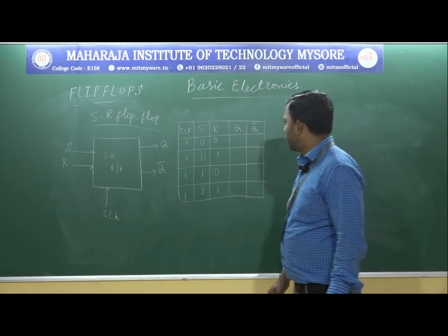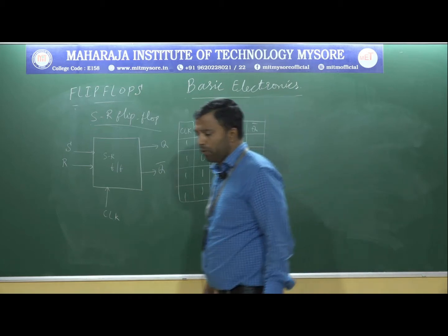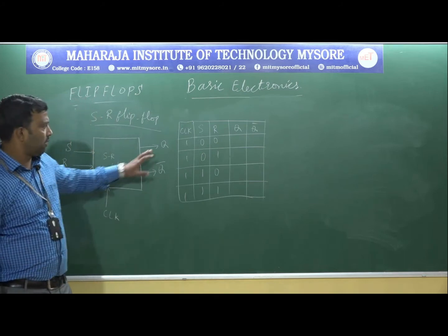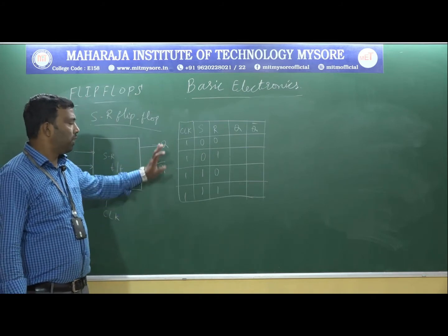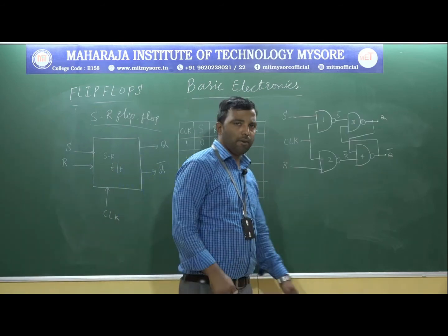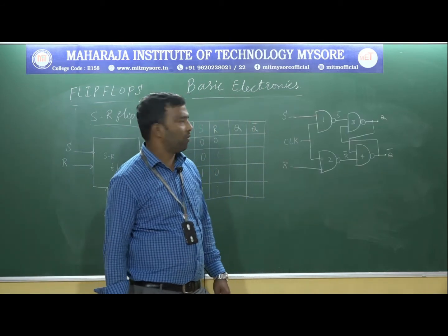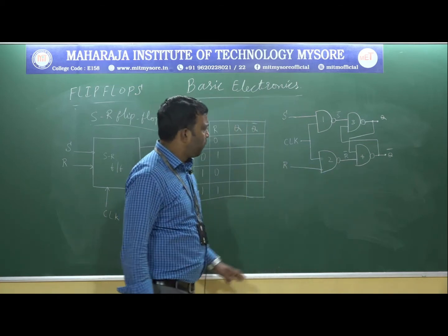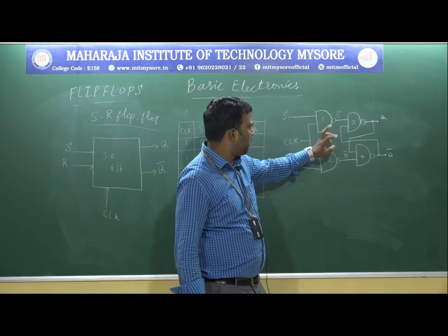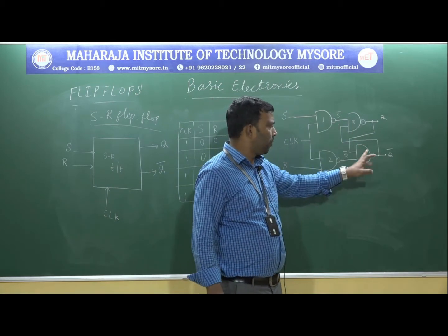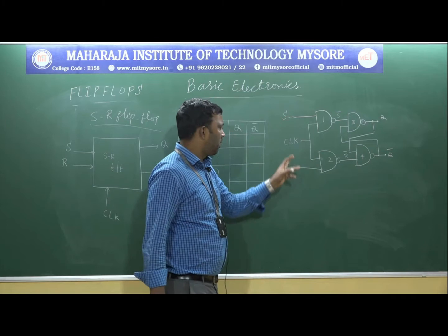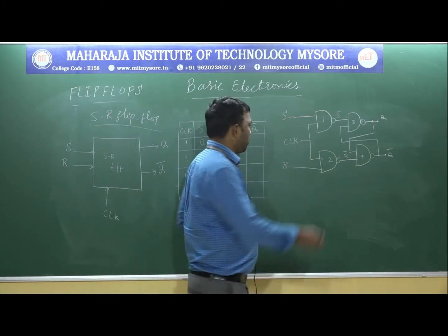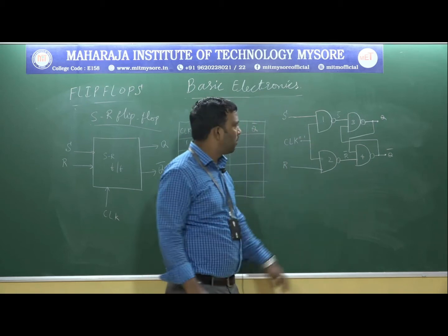Now SR flip-flop is a different case because there are 2 inputs and we are concentrating on the operation of the SR flip-flop. We will consider the operation of the SR flip-flop with the help of the NAND gate latch. So here the 4 NAND gates are numbered 1, 2, 3, 4. S and R are the 2 inputs for the SR flip-flop and clock is always equal to 1 for the operation.